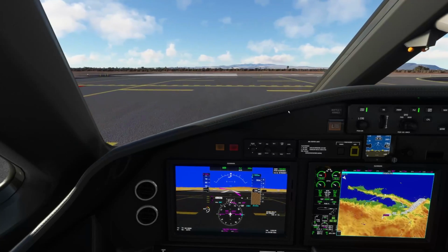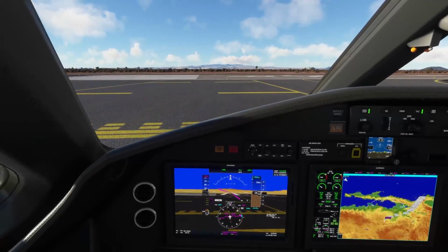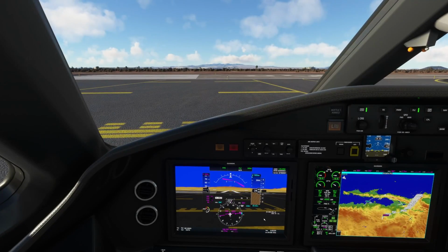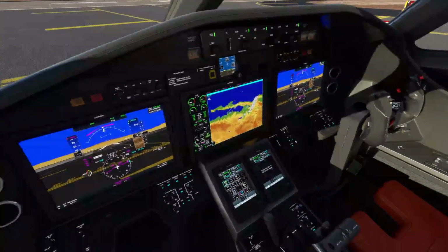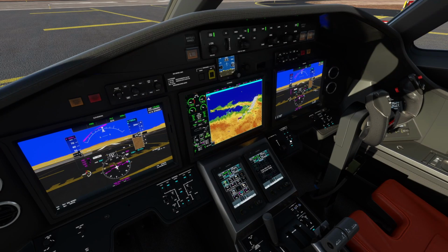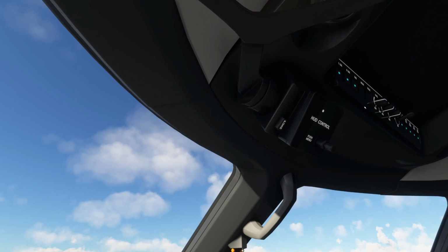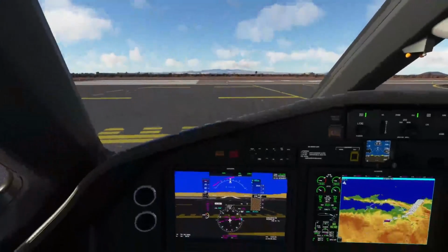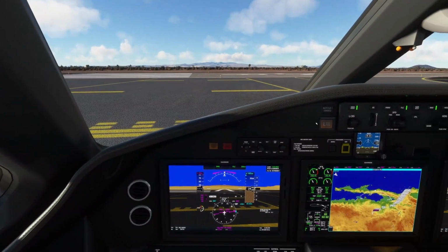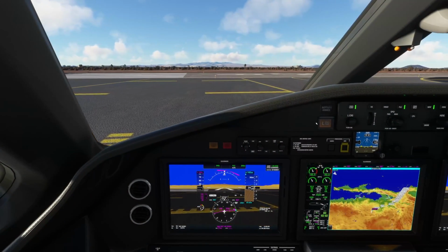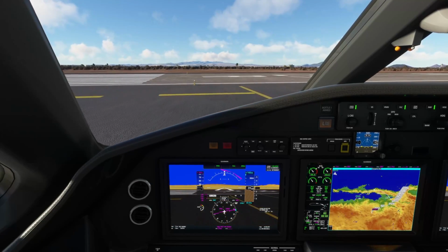Alright, getting ready to take the runway here. Came a little off course trying to get the recording started. I'm going to stop right here for just a second. We're going to go ahead and set flaps 1. Notice the no takeoff. Once I set the takeoff configuration, it went away. We're also going to step on over here, and these are our anti-ice. I'm just turning them on. There we go. And we're also going to bring the landing lights on. Notice that it turns off the recog and the pulse lights. And let's take the runway. We'll do one last check of the barometric pressure. Now it's showing 3004, interestingly enough.